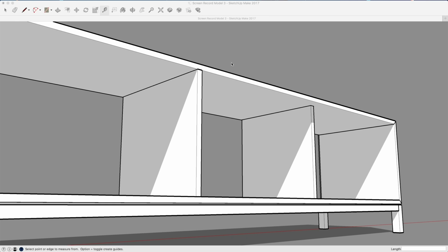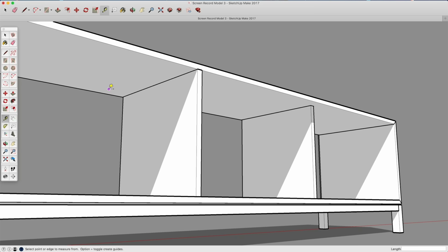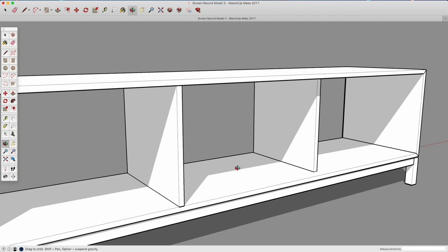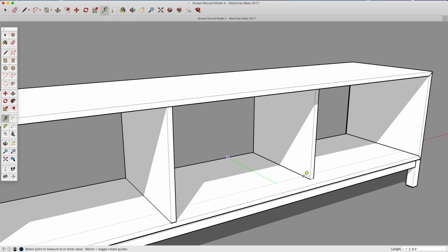But let's say that we want to use the Stopped Dado for this joint, which is probably what I would use most frequently. So to do that, the first thing that I'm going to do is make a guideline that represents where I want the dado in my cabinet to stop. So I'm going to choose 16.5 inches from the back inside corner. So I'll just drag along that direction and type 16.5 and hit enter.